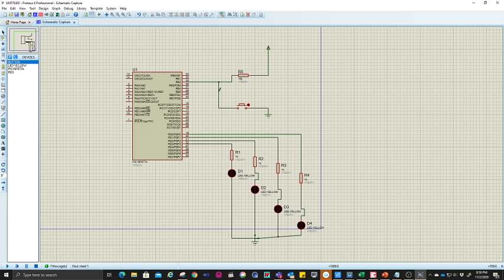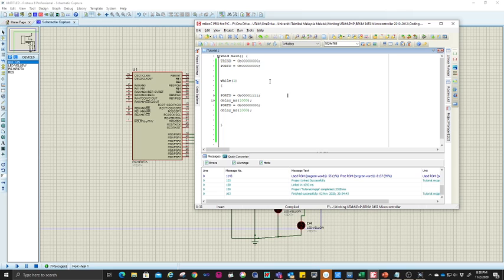So what I'm going to do right now is, I just want that if this pin is 0, then the whole LED will be turned on. If I release it, then the whole LED will be off. It's just like your lamp. So you just want to turn on by using a switch. So this is a configuration, but you can see you have to look here how you want to decide. So your port B2 is considered as the input. So you can go back to your Proteus MicroC again.